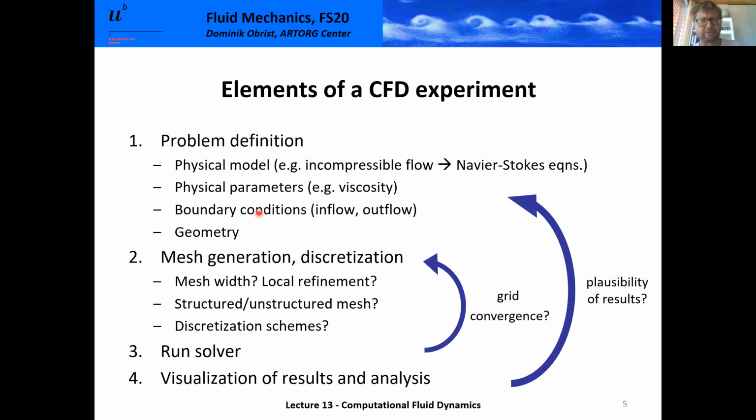You have a no-slip boundary condition, and there's no ambiguity about it. But just as you have the issue of putting a little model of an airfoil, of a wing, in a wind tunnel, and the wind tunnel has walls, and these walls, if they're too close to the wing, may affect the flow itself that you want to study.